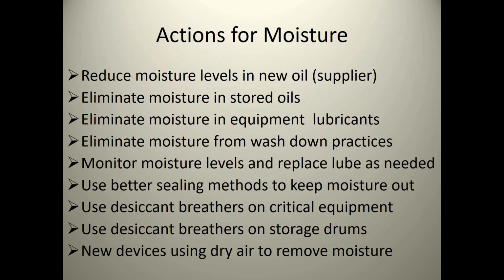So your actions for reducing moisture in oil, we talked about these the last time. Where's the moisture coming from? Well, it could be coming from your vendor. So I always recommend you go see your oil vendor. How are they storing your drums? How are they storing your buckets? How are they storing your greases? Are they controlled temperature-wise? Are they out of the weather? Are they away from moisture?